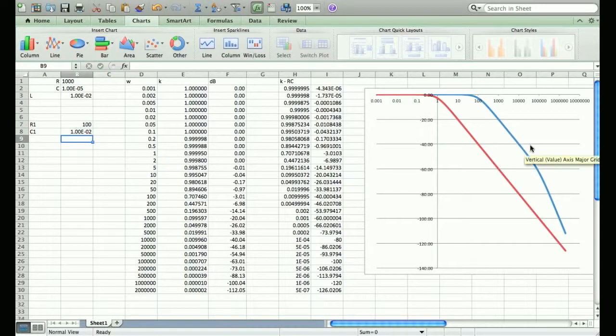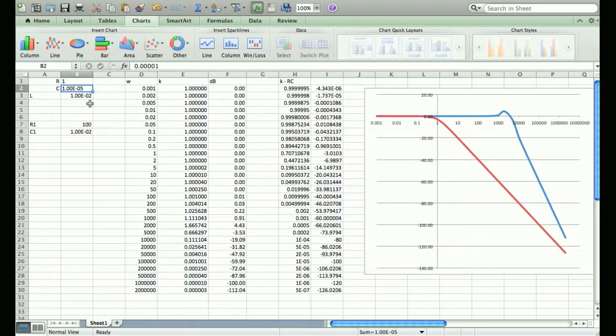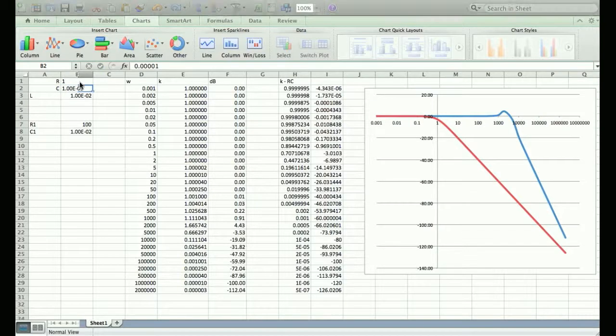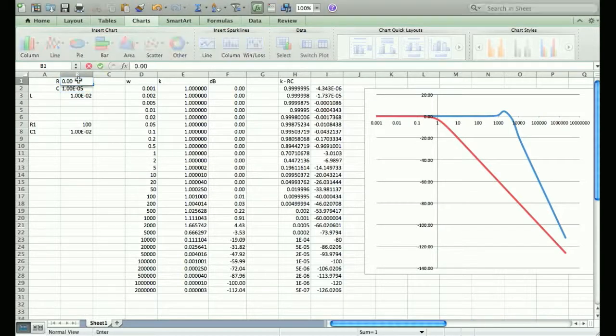Okay, so that's basically what happens when you have a solution to an RLC circuit where there's all imaginary parts, you get that resonance, where you wouldn't see that with an overdamped solution. You would never see that when you have something like a 1 kilo ohm resistor in there. So does that make sense? Does everybody kind of understand where the kinks are coming from? The roots of the characteristic equation.